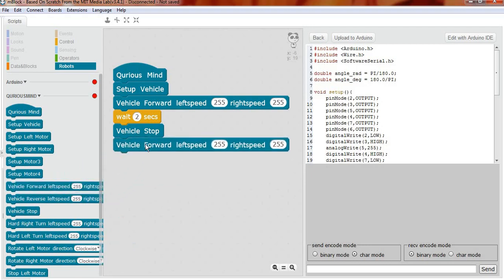So how will we achieve that? We'll make one of the speeds 0. Now what will happen if we make one of the speeds 0? One of the wheels is not rotating at all, but the second wheel is moving forward. It is not stopping. But as we know that the wheels are part of the vehicle, which means they are kind of connected to each other. So if one wheel is not moving, the other is moving, the vehicle will start rotating.